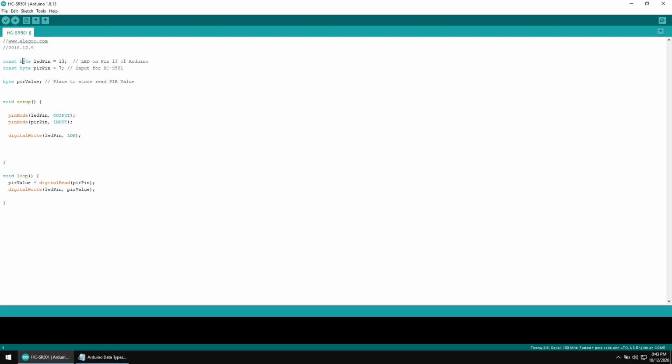You're using 8 bits and 8 bits when you're declaring the pins, LED pin 13, or PIR pin 7, but you're telling it it's a constant, so you're not loading any of this in RAM. You are loading this in RAM, but you have to, because obviously your program is going to be manipulating that. And if you have a lot of pins, like say you're using the Mega, that'll add up. If you're just going to declare everything as an integer, pin this, pin that, it's going to add up, especially if you're using most of the pins.